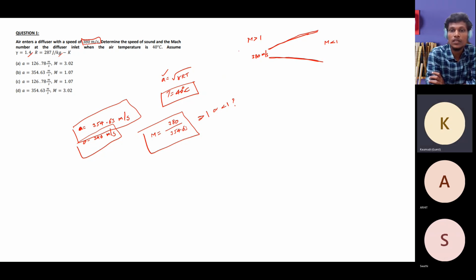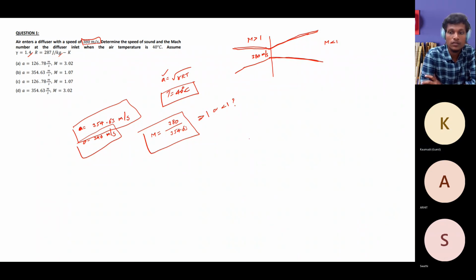I think it depends on the pressure at the exit of the diffuser. Yes, it depends on the exit pressure. Also, you can modify the inlet pressure. But what phenomena should happen inside this diffuser section if my Mach number at the inlet of the diffuser is greater than 1, and at exit it is less than 1?